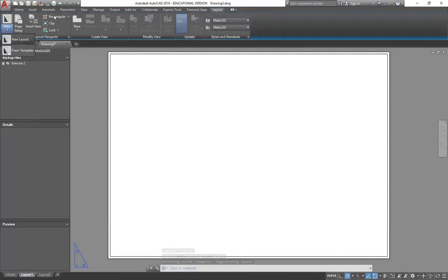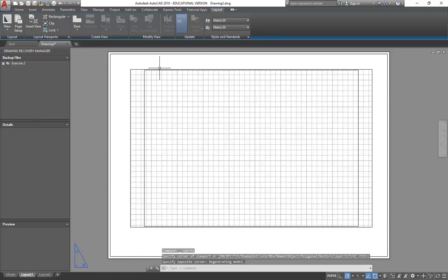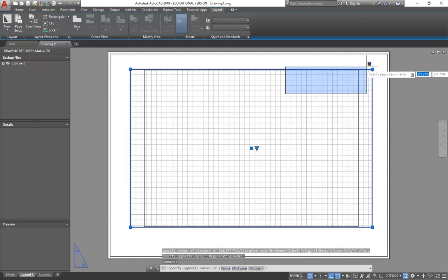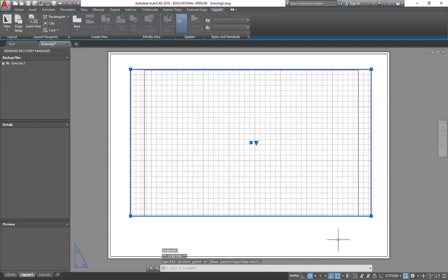It's the rectangular button. So there's no viewport option there, but rectangular, and all of these basically are for viewport. So you have to go rectangular, and then you can click 2 points and make a viewport. So you could put multiple viewports in. Exactly. So when you're setting up your default page, you might just have a viewport that's a generic size, but you can always make as many as you want.